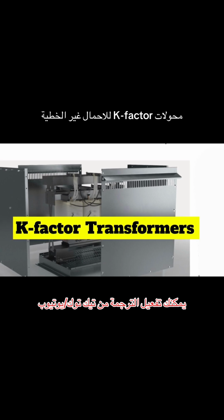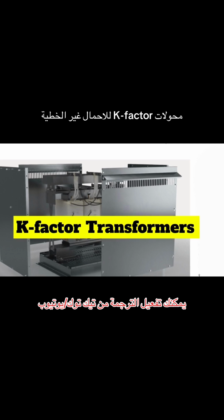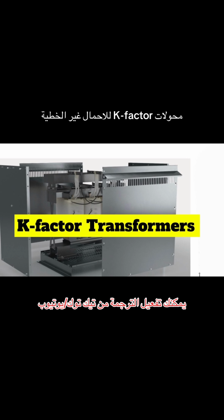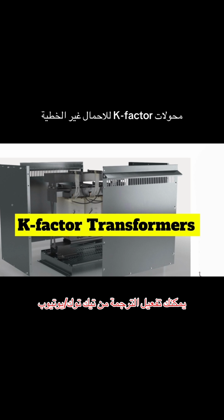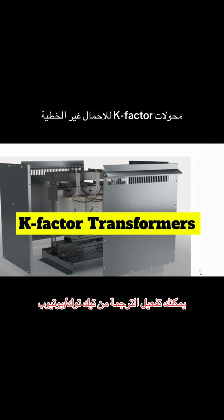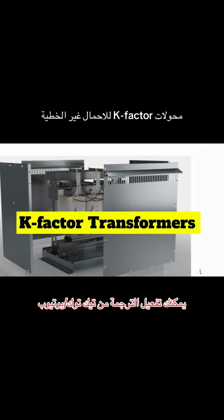Now, the paper has this really handy table that gives general guidelines for K factor ratings based on the type of application. Let's walk through a few examples so our listeners can see how this applies in the real world. Sounds good. Okay, so a K1 rating is suitable for your basic, everyday applications with minimal harmonic generating loads. Think standard incandescent lighting, simple motors without variable speed controls, things like that. In these cases, the total harmonic distortion is usually less than 15%. Right, the simpler stuff. Exactly.